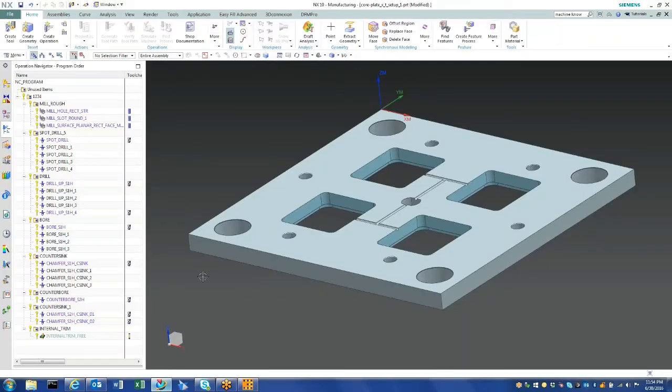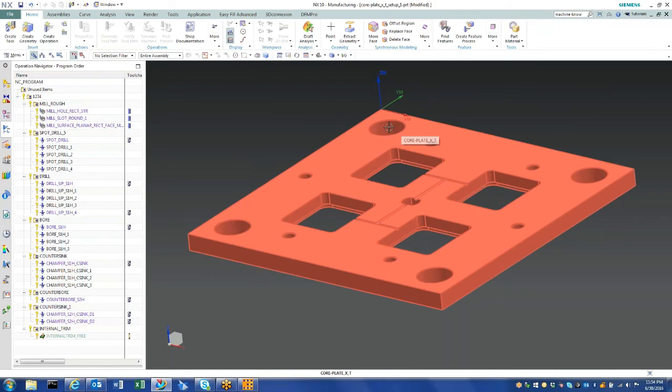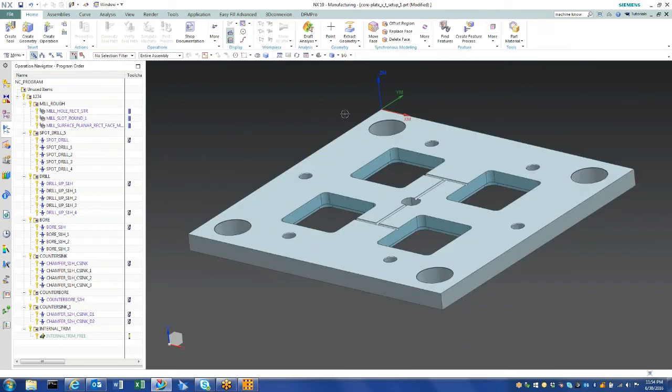First, NX runs the engine to find its own features or other features with the rules that are in the knowledge editor. Then NX takes the features that were found, cross-references them with operation data, and finds a tool that can create that feature. Then NX takes that tool and that feature and creates a feature process, which is your operations, to make the hole. So it's a very robust, very powerful tool.